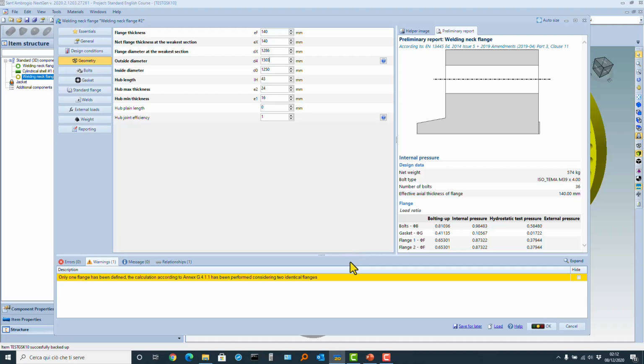Check is okay. Look, now we have reduced also the dimension of the outside diameter, the dimension of the bolt circle. We have 574 kilograms. The advantage in weight is something more, because the original weight of the flange, well, can you still reduce a little bit the thickness? Here there is a 0.87, say for example 135 here and 135 here.